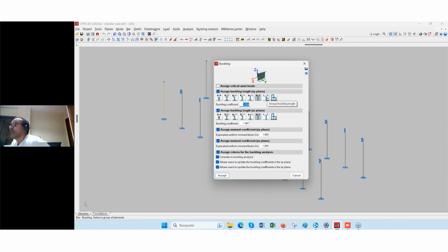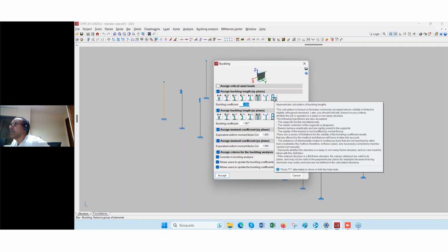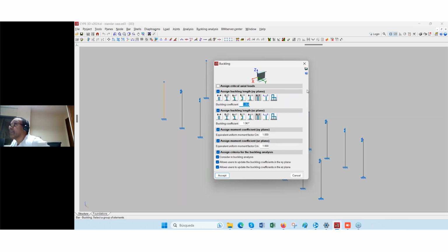You can put this coefficient according to the case you have. You can also put directly the length you want, and you can use a simplified method to generate it. So in the implementation we did, we use an advanced mode to help you calculate the effective length. In this case, we will give you the coefficient to multiply the section length you have and describe the bar.